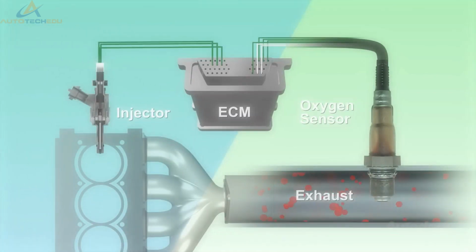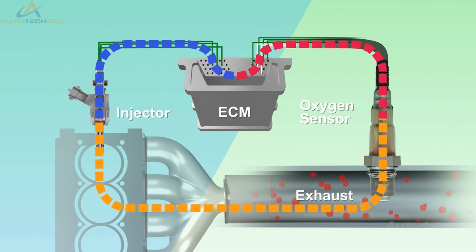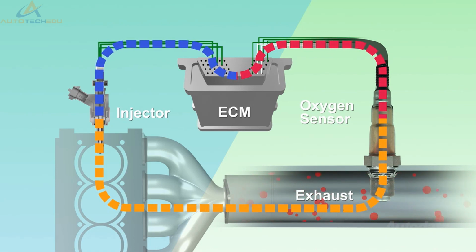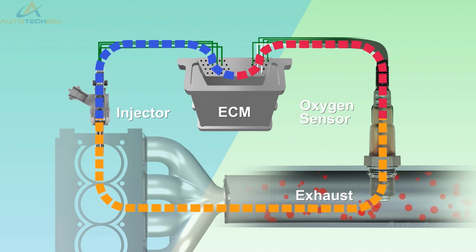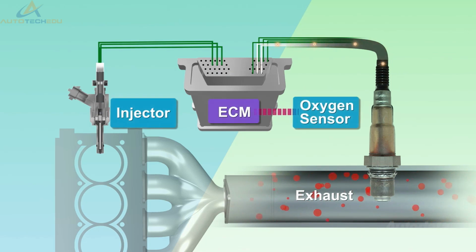The Engine Control Module, or ECM, controls a closed-loop air-fuel metering system in order to provide the best possible combination of drivability, fuel economy and emission control. The ECM monitors the upstream oxygen sensor signals and fine-tunes the fuel delivery based on this signal once the engine